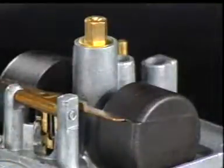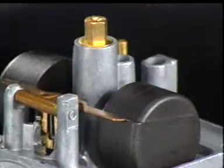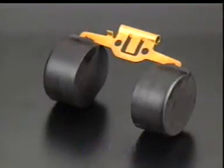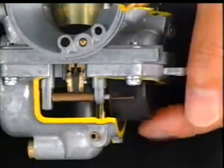In order to supply a stable mixture of fuel and air to the engine, the float section is designed to make sure that the level of fuel that has accumulated in the carburetor remains constant. The float section consists of a float suspended on the fuel inside the float chamber and a needle valve which is joined to the float and moves together with it.